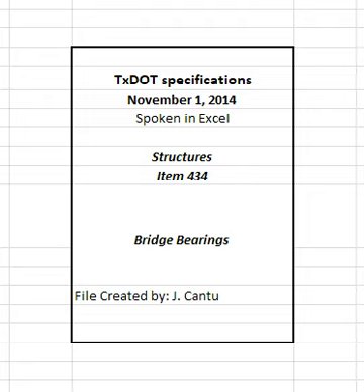2.3.3.4 Supporting masonry plate and anchor rods. Coordinate any necessary adjustments to masonry plate geometry, connection method, or grout interface with the engineer to ensure compatibility with the structure design before ordering any materials. Provide medium strength, mild steel, or better type anchor rods in accordance with item 449, anchor bolts, including nuts and washers, unless indicated otherwise on the plans.